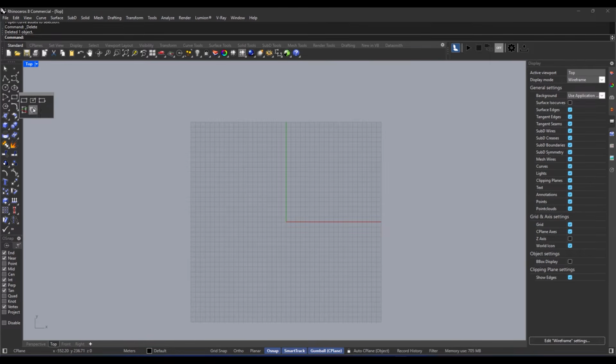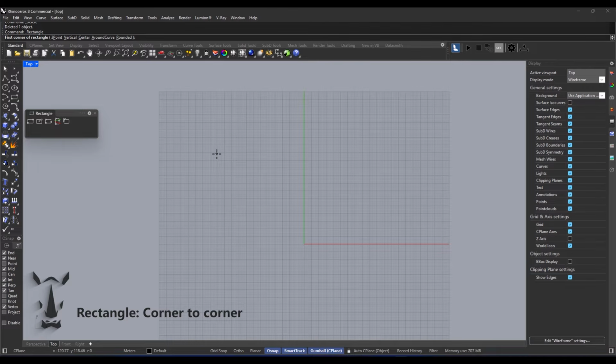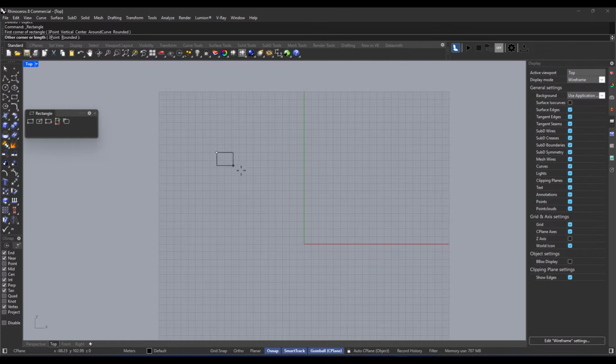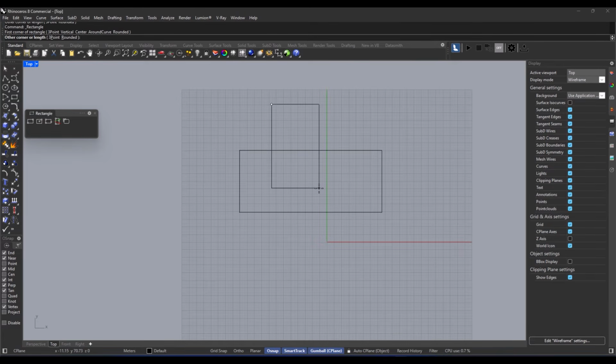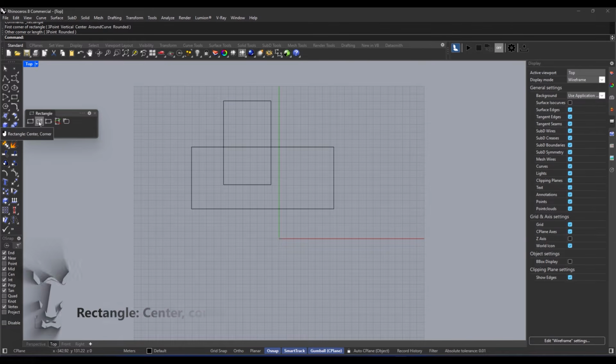Okay, so we're talking about rectangles here. This is all about different methods for drawing squares and rectangles. First off, there's corner to corner. Basically, you use 2 opposite corners to create a closed rectangular polyline. Super simple, you just pick your 2 points, boom, that's your rectangle. And then there's another method, center corner. You start from the center point and then head out to a corner.